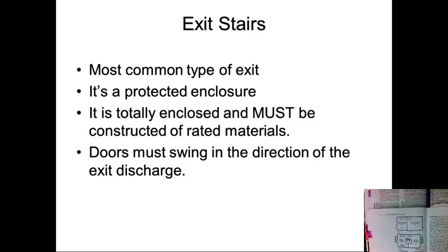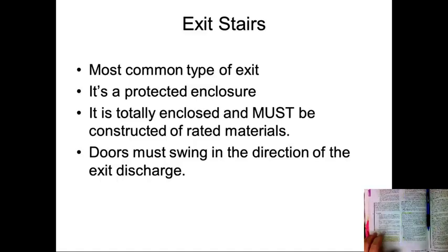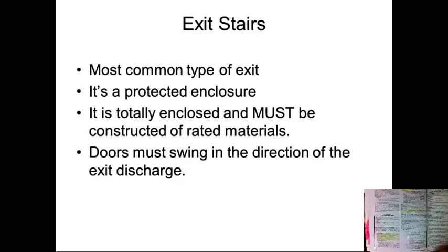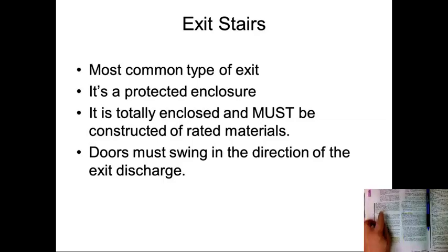In addition, I want to point out that in your IBC code book there's a whole section on stairways. Under section 1007, you see stairways, in order to be considered an accessible means of egress. So you need to look up a lot of the different parts of a stairway. Go to the back of your IBC code book, look up exit stairs, and it will give you every page that you need to be familiar with.